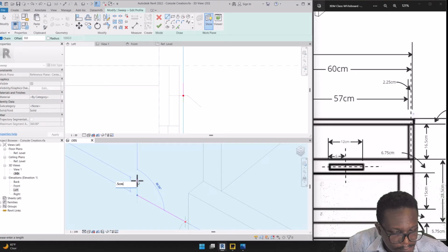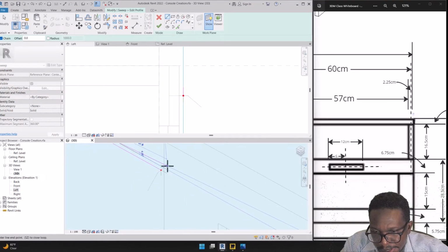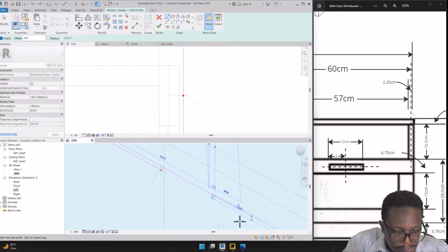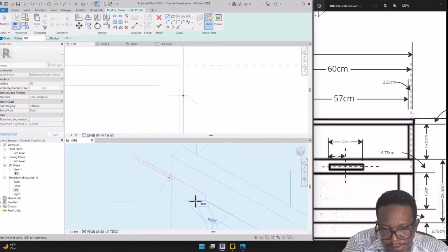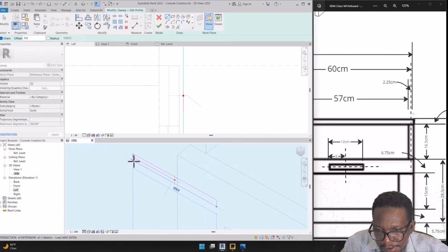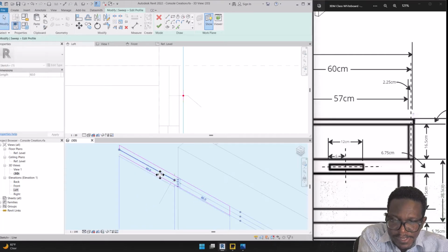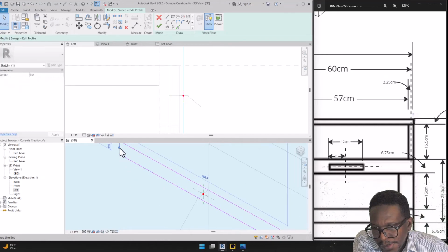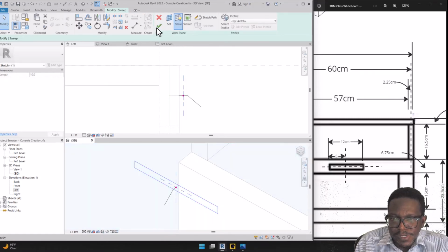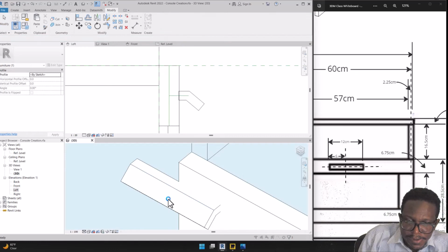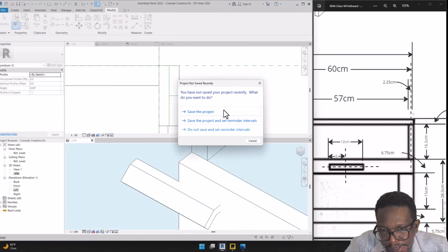Yes, and then we're going to go up 0.5 centimeters, and we're going to go across 12 centimeters, and then we're going to go down 1 centimeter, come back across here, and we can just delete this first line here, because we'll just use that to help us draw this real quick, and we'll just join this up here, and that gives us our shape, and we choose OK and OK again, and then we will get our sweep just fine.